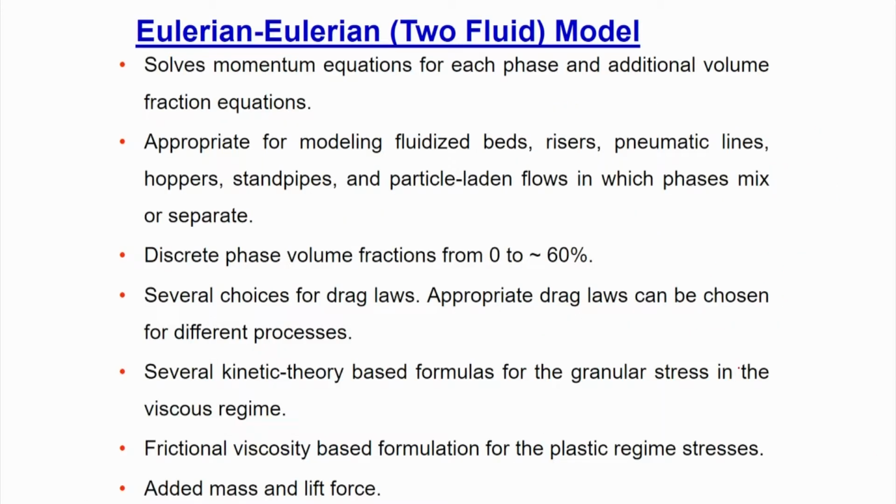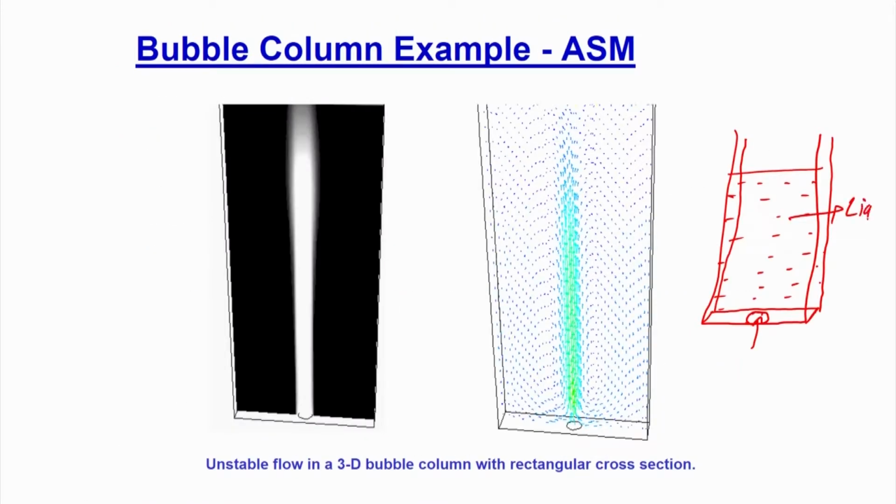So, this is liquid and this is the air. Air is passed. So, what will happen? The air will lift at the center. Once the bubble lifts here at this location, the velocity is very low, so the bubble fraction is very low. The bubble will lift in this way, and liquid will move upward at the center of the column, which you can see here. Most of the bubble fraction will be at the center of the column. You can see here the air fraction at the center of the column; the white color shows air, this is air and this is liquid or water.